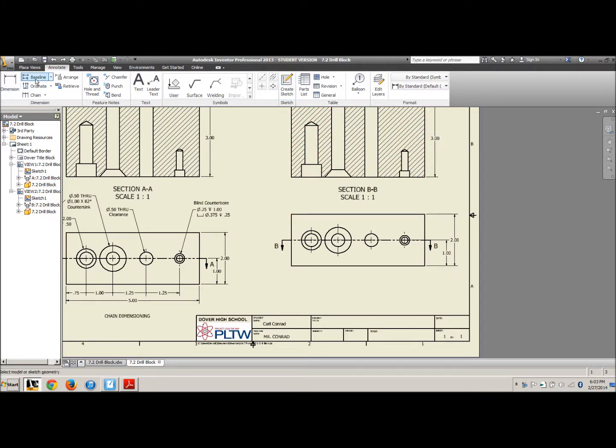So I guess let me do the datum dimensioning for all the holes first. Just click all my center points. Of course, I've already used the center point tool to create those. Whoops, one more. Baseline. Click all my center points. And that brings in all the baselines.